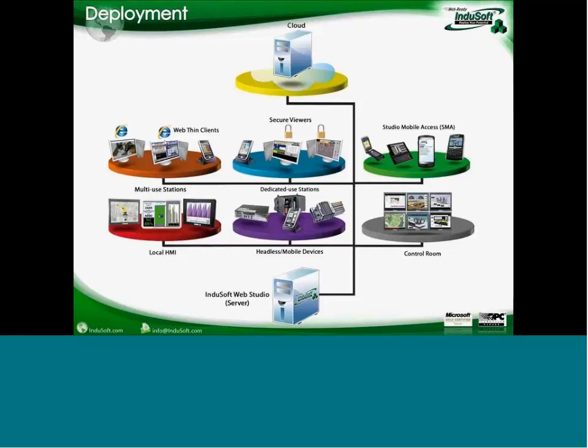We also have the secure viewer thin clients, which is very common in large machines where you need more than one HMI. But instead of installing InduSoft Web Studio and the application in each one of the stations, you can install in just one. And in the other stations, you just use a secure viewer thin client, a terminal that has access to all the screens, all the information. The user can navigate through different screens individually on each thin client, but still they share the application that is running on the runtime station, on the server station.